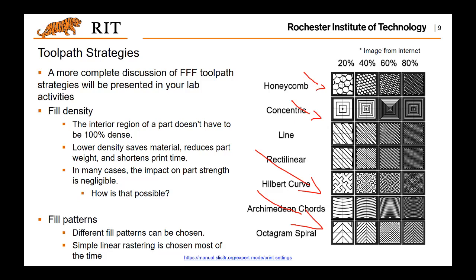That is because we figured out that most of the rigidity or strength is contributed by the strength of the skin, that is, the profile of the layer. And so that makes things simpler. That means you don't need to worry too much about these infill patterns. You just choose one of them, and that's it. Probably you want to think about the strength-to-weight ratio. That's the only thing you want to take into account when you choose the infill percentage.